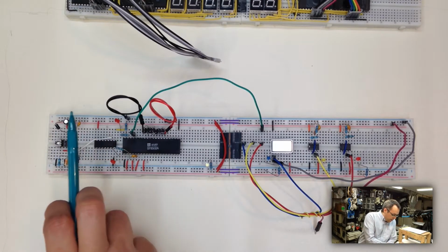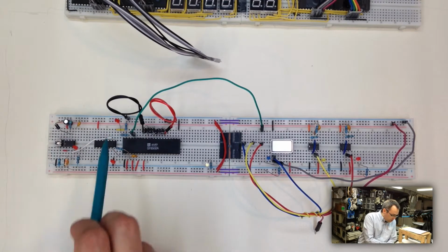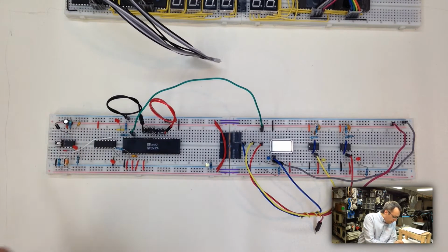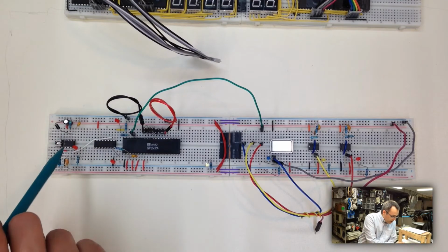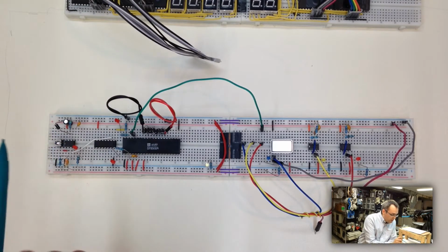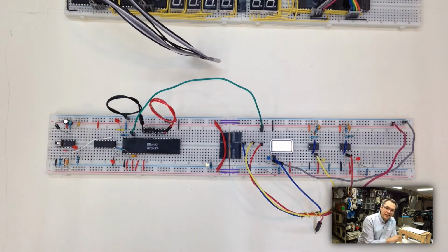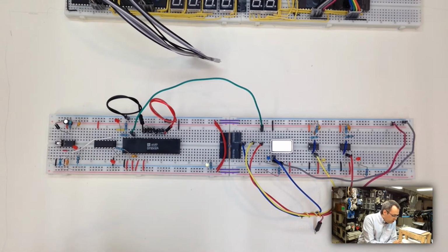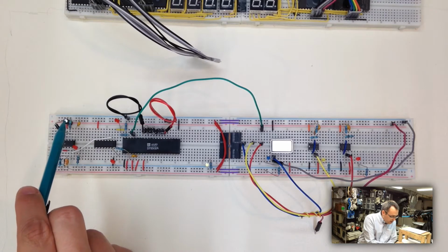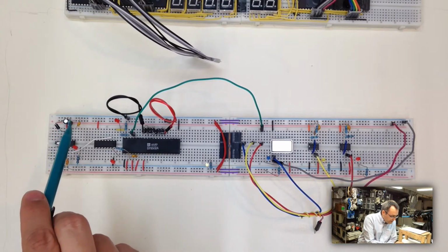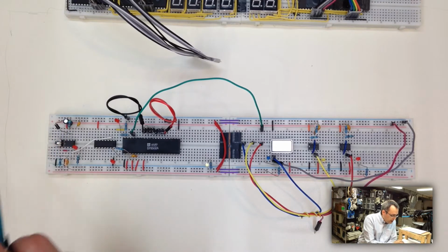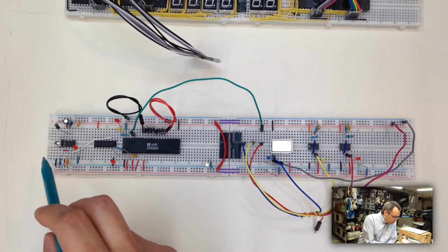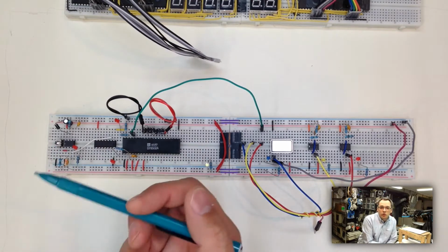So the first thing is this half of the board here, these 2 chips and all of this support circuitry here. This is our power on reset or auto reset circuit. Basically, it's a 555 timer combined with an inverter that when it receives power, in monostable mode, will strobe a single pulse out to the reset pin of the 6502. It's set up with a 10 mic capacitor and a 47K resistor here that in combination give me approximately half a second of pulse, which should give us plenty of pulse to get the machine bootstrapped and working correctly.